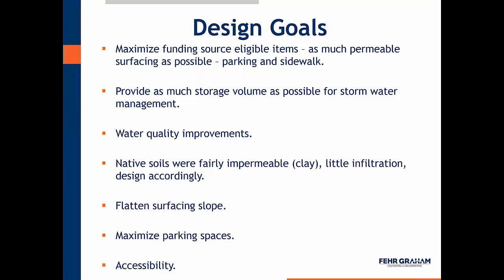and quantity. So we have a parking lot. Most parking lots have a sidewalk that goes with it. We want to maximize the eligible items, so we are looking at permeable surfacing for the sidewalk and parking lot both, really as much as we could possibly get in. Also, stormwater quantity reduction, so we're looking to provide as much storage volume as possible for stormwater management. Water quality improvements, that was one of the main goals of the grant, so obviously that's a main part of